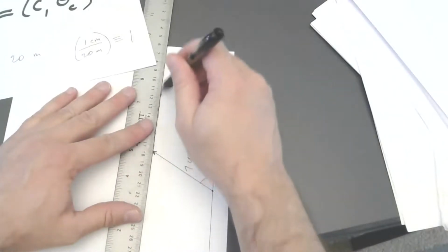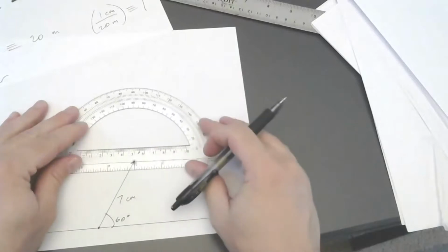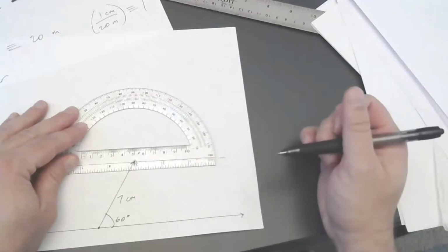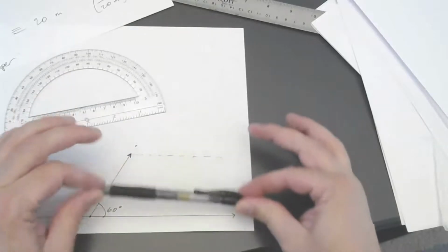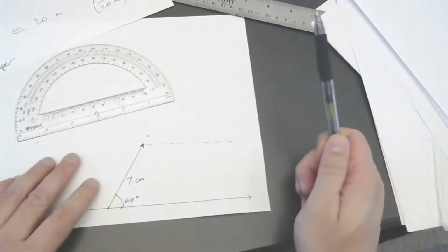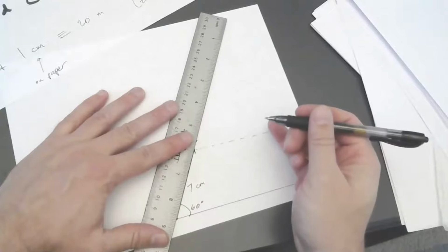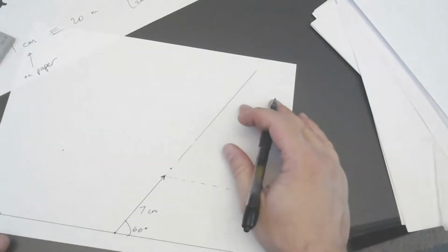And I can try to sketch a line parallel to the x-axis, and then put my protractor there now so that the hole lines up with the tip of vector A, and repeat that procedure, this time marking off 110. What's the problem with that, though? I'm just using my eyes to judge that this line is parallel to this one, and that means that I'm introducing error. So what would be better is to extend vector A. It's almost like you're making a new axis. And if I want to draw vector B,